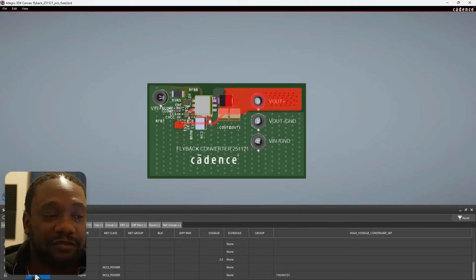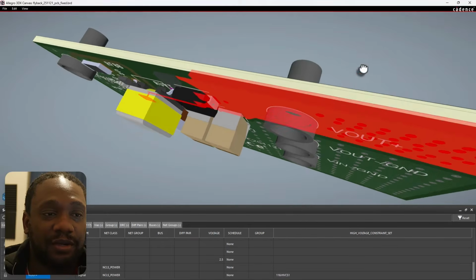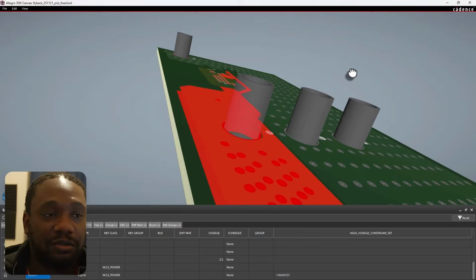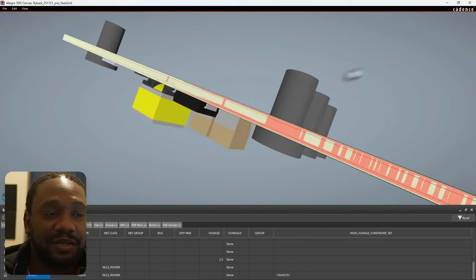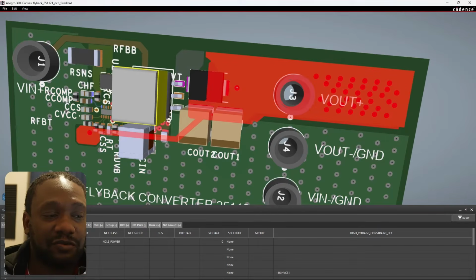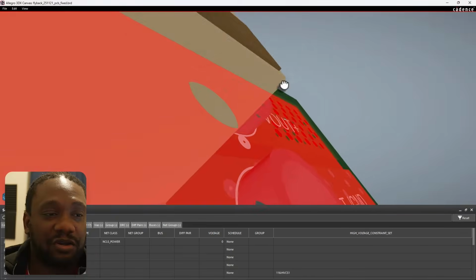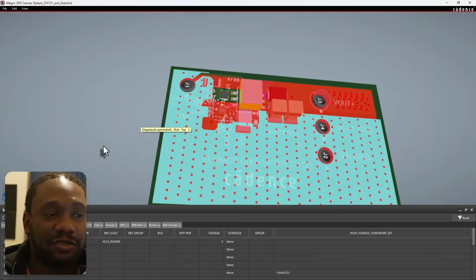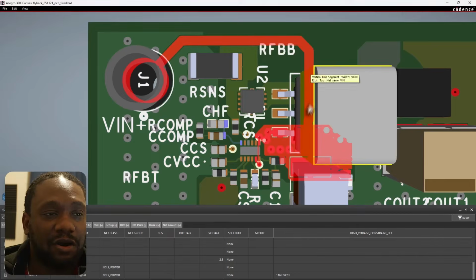So if I look at V out plus, it's on layer 1 and layer 4. The top and bottom layers of this PCB. The internal layers are both ground. I have return paths for my V out because that's part of hot loop 2 as well. Okay. Then of course for V in, we have our trace.